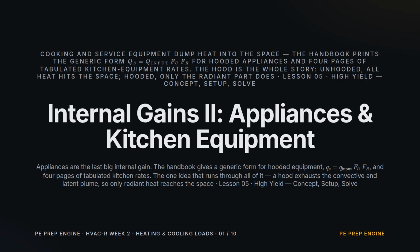Week 2, Lesson 5, Internal Gains, Part 2, Appliances and Kitchen Equipment. This is the last major internal gain. The handbook prints a generic equation for hooded appliances and 4 pages of tabulated kitchen rates. One idea ties all of it together. A hood pulls the convective and latent plume up the duct, so only the radiant heat reaches the room. We'll ground that, then work a hooded versus unhooded gain.